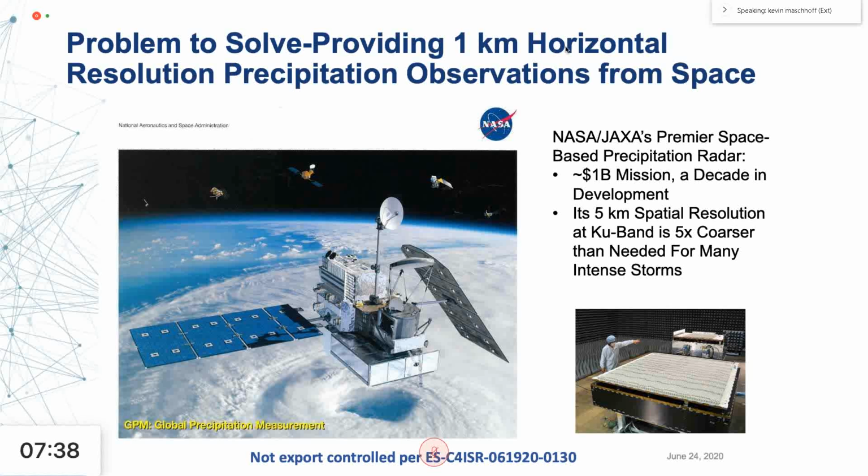And the specific technical challenge with respect to convective storm observations from space, particularly mid-latitude storms, is that the spatial resolving power of this approach is diffraction limited at several kilometers, close to 5 kilometers spatial resolution in Ka band, which is the primary band used for the more intense, more absorptive storms. You can see in the lower right panel the relative scale of this antenna. So the problem is, how would one actually go to a much larger antenna in order to obtain the higher spatial resolution using the real aperture method? There are certainly other design implementations than using a large phased array radar, large area reflectors, and so forth that could be employed in a different design concept. But the underlying problem is that they're all going to be large and therefore costly to develop and deploy in space.